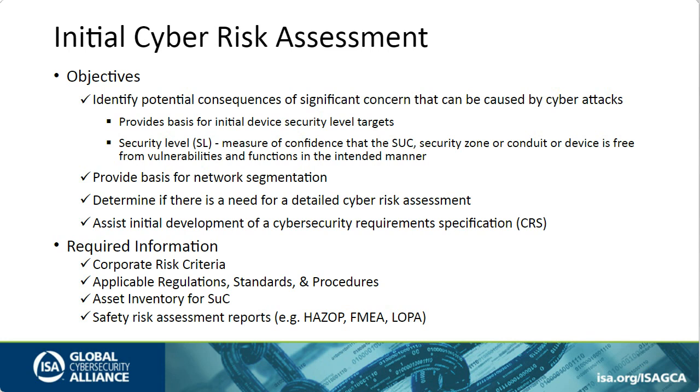So going through the initial risk assessment, you're hoping to be able to assign security level targets, which in turn is a valuable input to when you partition the architecture into zones and conduits. Also, once you've done that and you've looked at your consequences and compared them to your risk matrix, you'll figure out whether or not you really need to do a detailed cyber risk assessment.